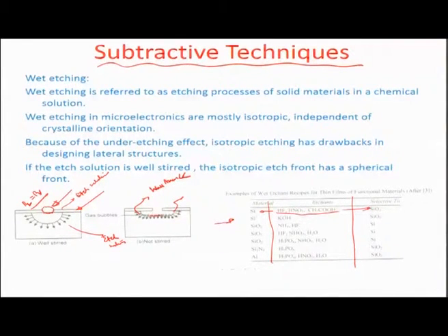That means this particular area, which is subjected to etch, let us call it the flat area, would have more etching, and if you are not having a removal mechanism, it is going to accumulate the etched out particles and create a concentration around the flat, because of which further movement of the etchant towards the flat may be severely limited, and because of which there may be a case of under etching or lateral etching, you can say,